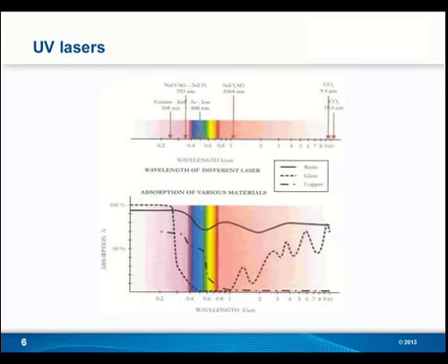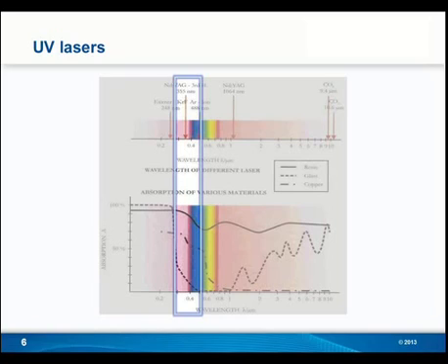Backing up just a step to highlight the CO2 lasers, you can see very good absorption for resin, very good absorption for glass, but there's very little absorption for copper. Finally, the other laser I wanted to point out is the Excimer Laser on the left. The Excimer Laser measures very well in absorption rate for the three different materials we're looking at, but most people are priced out on Excimer lasers, and so that makes UV a very good option for everything in between.